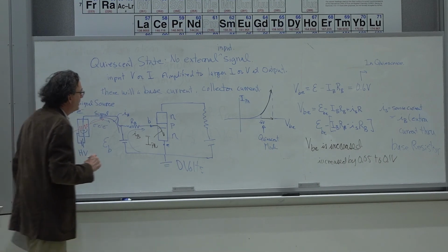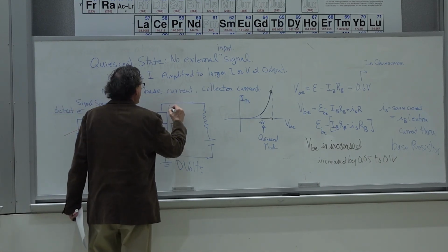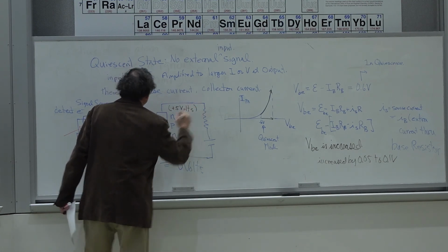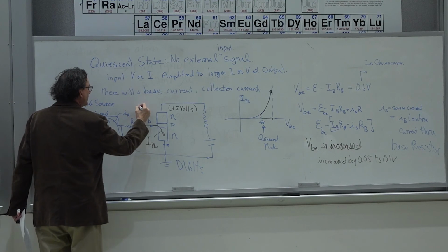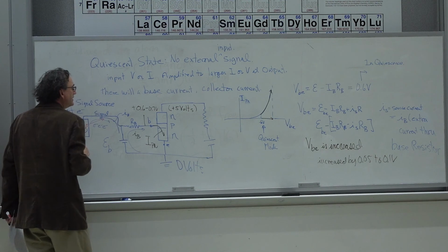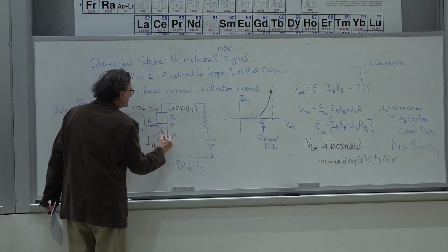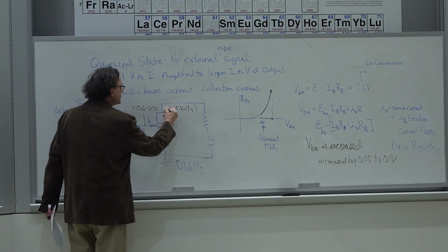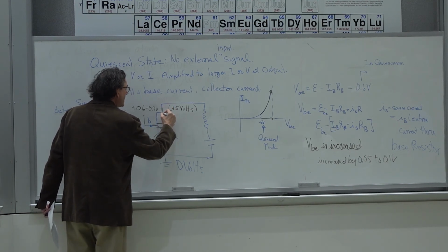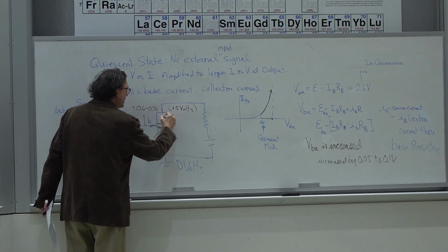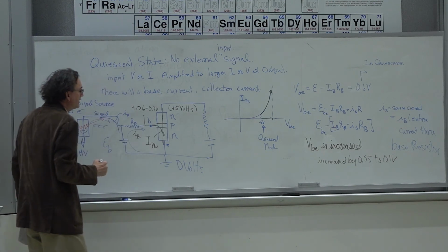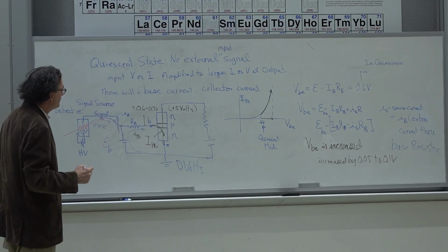And furthermore, because this is sitting at even higher potential, for example, around plus 5 volts, compared to this, which is sitting at around 0.6 to 0.7 volts positive, then when this begins to conduct, this one also begins to conduct, because this region is so thin that the current can now simply propagate straight through the junction of the negative carrier and the positive carrier.